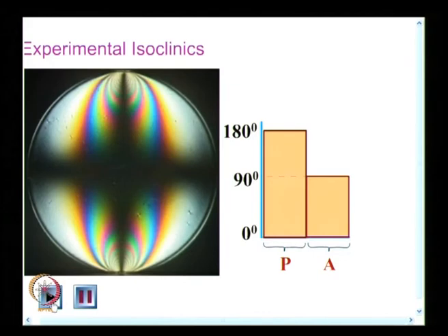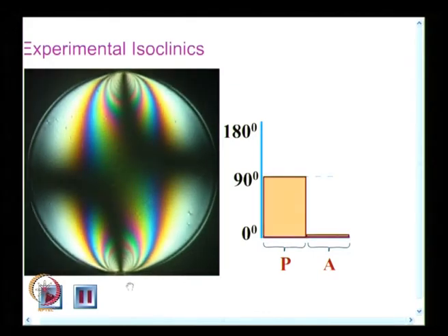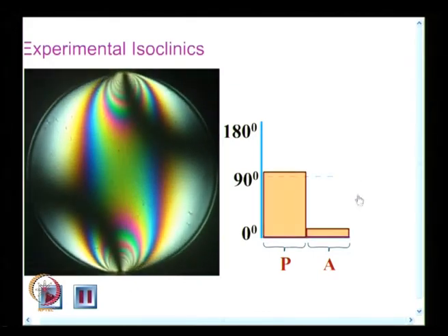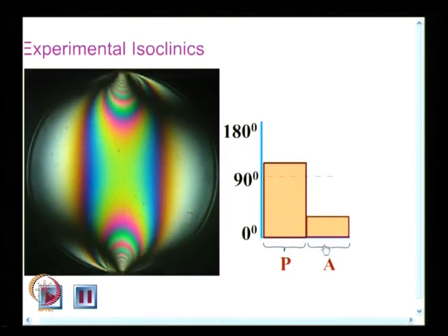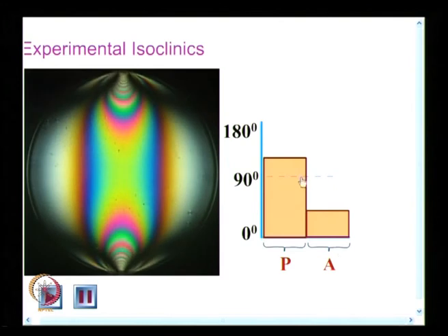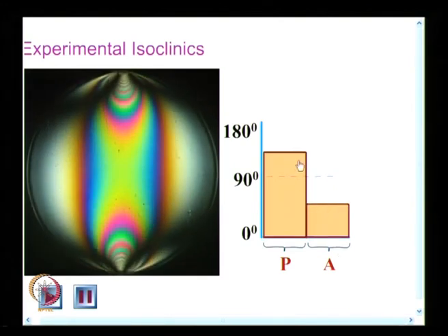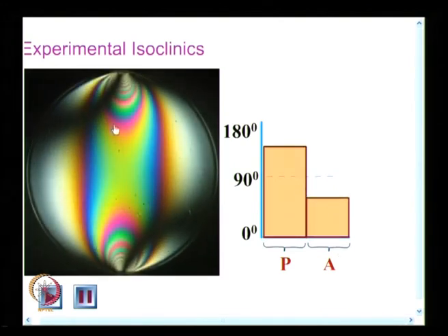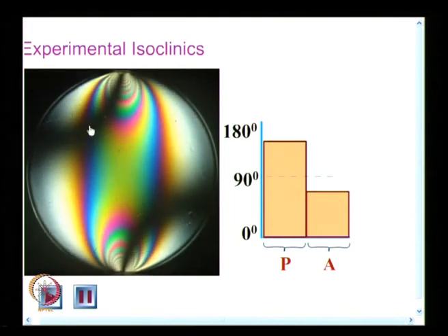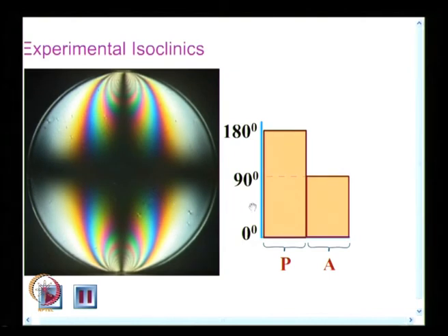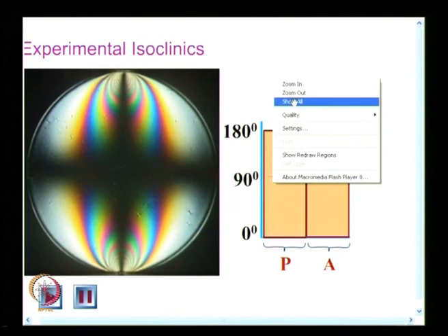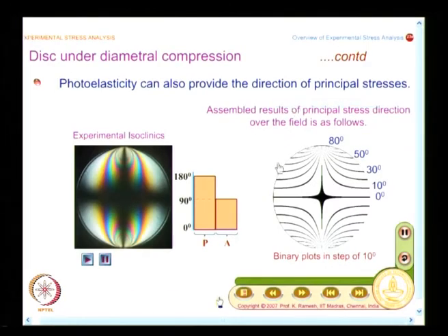And in this example, I have one set of contours that move, and you may not be able to understand this at this stage. What it indicates is the direction of the polarizer and analyzer. These are two optical elements, kept at mutually perpendicular angles. For these angles, these contours move. So, from a data collection point of view, I have to set it at fixed angles and try to make a reasonable sketch of what these contours are, and that is what is shown here.